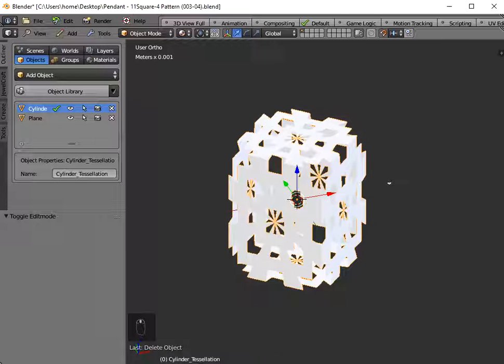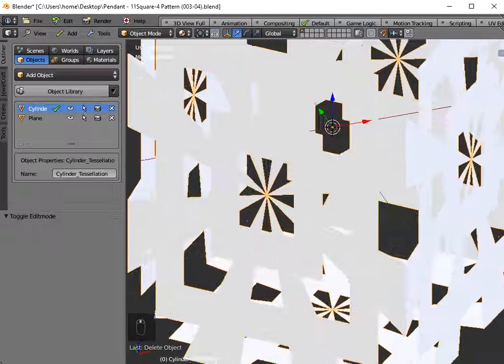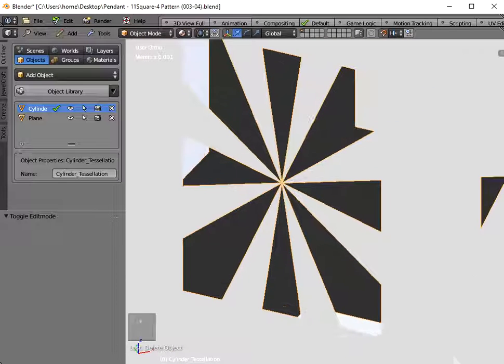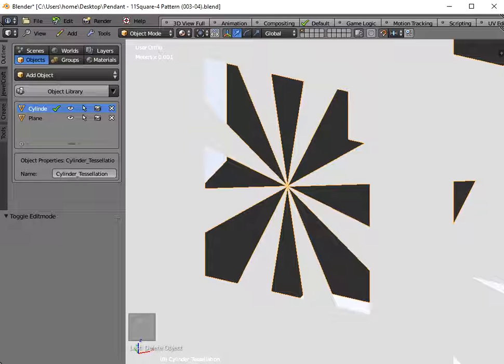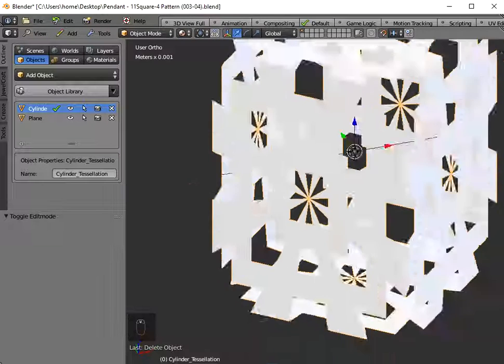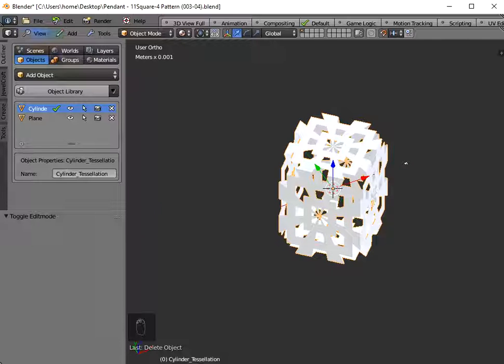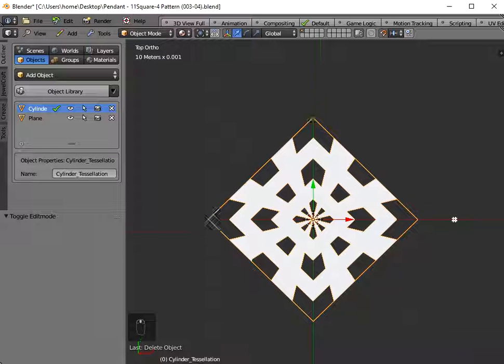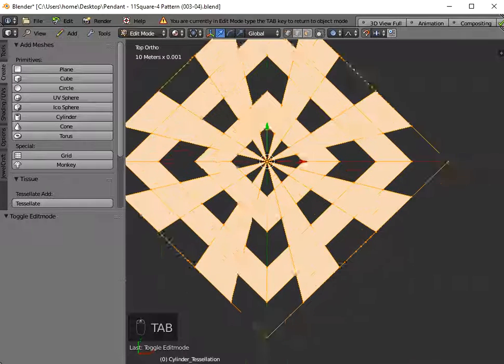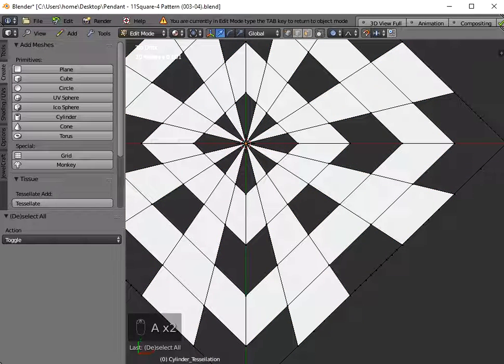Now, I know from experience that when it comes to 3D printing, these parts here in the middle of the screen won't print very well at all, and in fact they'll fail in NetFab Basic. They're too narrow and there's multiple points at the center, so you do need to delete those. So if we go to View and Top View, what I would do is press the Tab key to go into edit mode, A to deselect all the points, and C for circle mode, and just highlight the vertices in the center. Press the Escape key to come out of circle edit mode, and X to delete those vertices.